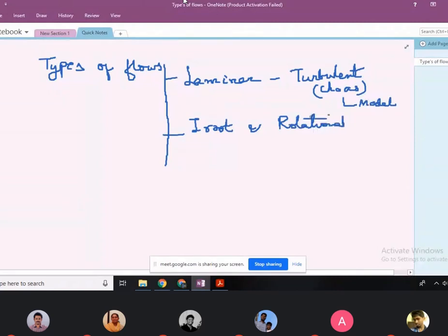Here we understood that irrotationality is mostly associated with the flow being inviscid. Such flows are called potential flows. Irrotational inviscid flows are called potential flows. If you use a solver to solve your problem, you can see that you are able to select inviscid flow.